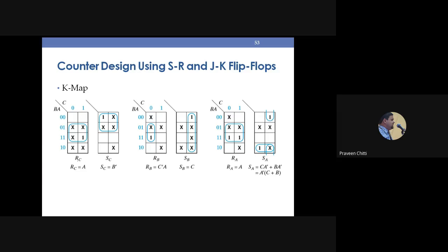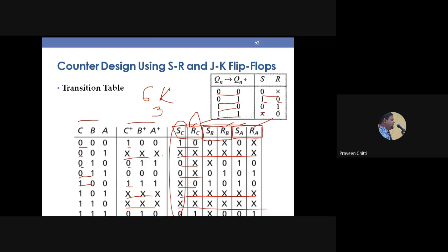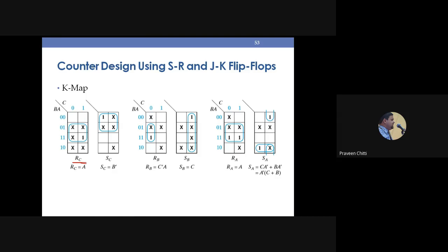What all should you enter here? I'll take this example RC. So what do we have in the RC? You can see 0, X, X, X, 0, X, X, 1. All are X, only the 0th, 5th, and 7th differ. It is 001. You can see here the 0th, right? Actually, the 0th is 00. These two are 00, they are not shown. This is 1 and X, right? This is 001X. So how will you do the grouping?